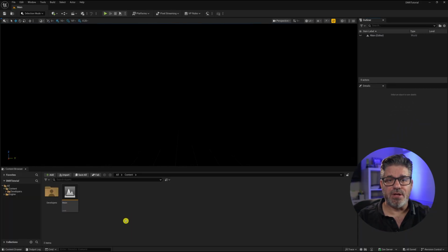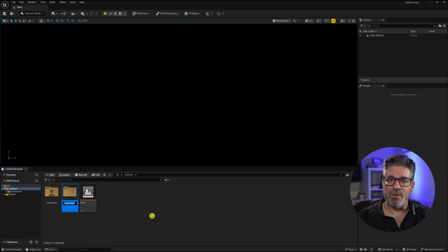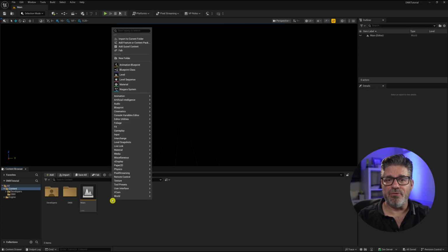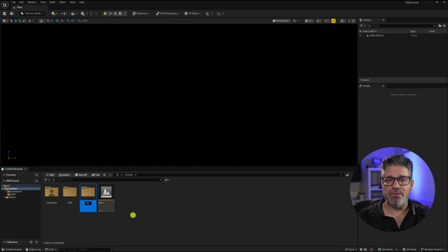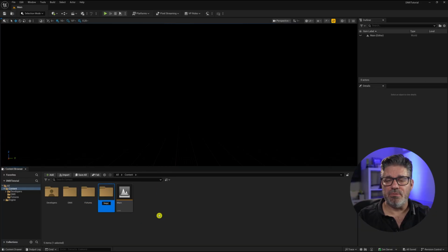So we're here in the top level content folder. Right-click in the content browser and select New Folder. Let's title this first one DMX. Go ahead and right-click again and then make another folder, and we're going to say Fixtures. One more time, we'll call this one Sequences. And we'll do one last folder, we'll call this Maps.